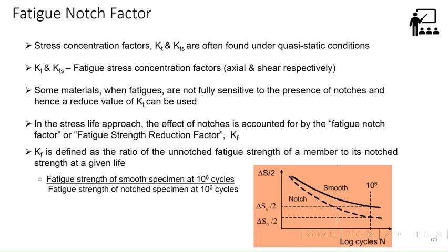So what do you expect? Kf, is it 0, equal to 1, greater than 1, or less than 1? Of course it cannot be 0, it has to have a value, but is it equal to 1, less than, or greater? The clue is there in front of you, the figure. Correct, because you are comparing fatigue strength at 10 to the power 6, this is greater than this value, right? Obviously it will come out greater than 1.